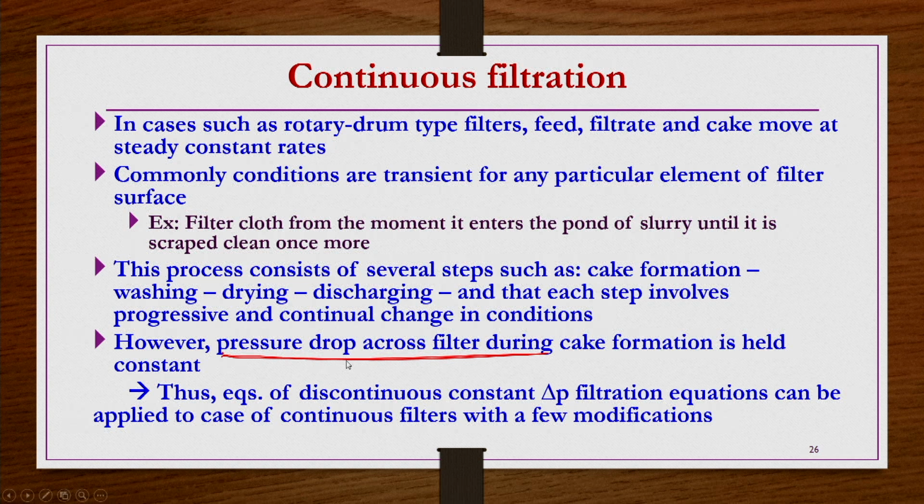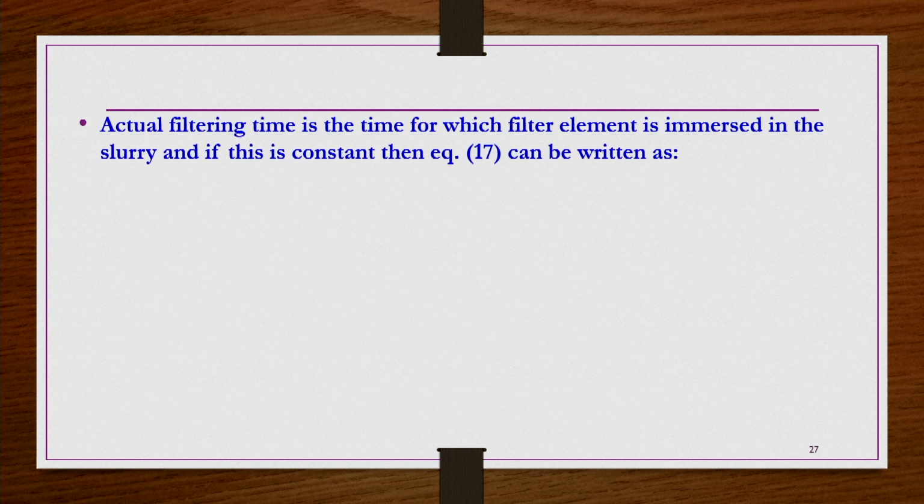Since the pressure drop across the filter medium is maintained constant during the cake formation, whatever discontinuous or batch constant pressure drop filtration equations there are can be applied to the case of continuous filters as well, with a few modifications. What are those modifications? Actual filtering time is the time for which the filter element is immersed in the slurry, and